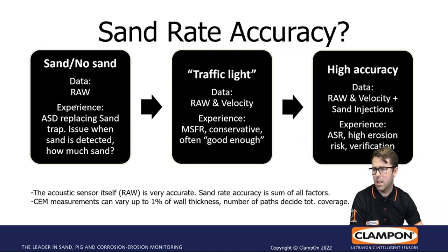The problem is if you start to produce sand and you have a system like this, you have a big issue, because then you have to start collecting the velocity, start calculating the sand rate, etc. And it's not possible to implement that in the system in a day or two. It takes time to change things, how it's integrated into the control system, etc.